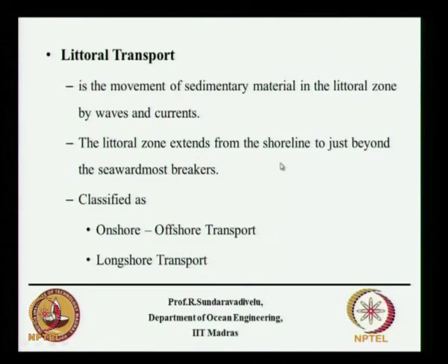So the littoral zone extends from the shoreline to just beyond the seaward most breakers. I said already the breaker is H by d equal to 0.78, and we have different types of transport. One is called the onshore offshore transport, that is from the offshore to the onshore. Another is the longshore transport, that is along the shoreline. This along the shoreline transport is obstructed by breakwaters. So we have the transport.